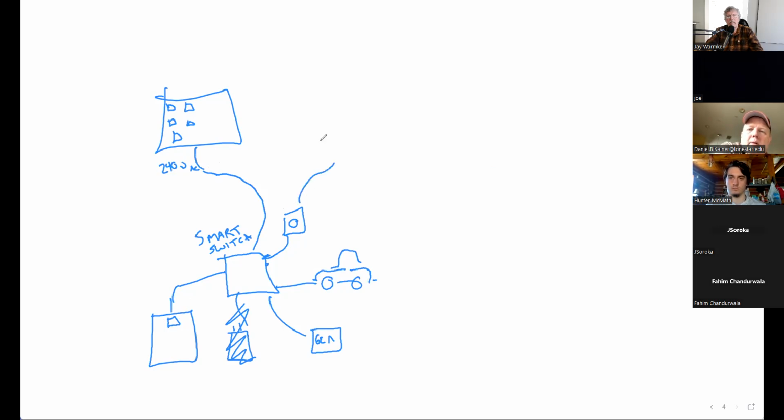So then from here, this is the grid. If I have too much power, it's going to send it out to the grid. Then as soon as it loses sight of the grid, it's going to disconnect here. And now everything operates independent, like a standalone system. And I can use the battery backup from my car to run my home if I need to.